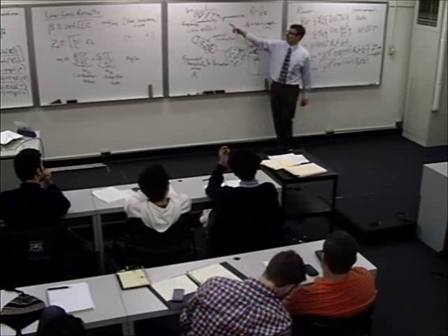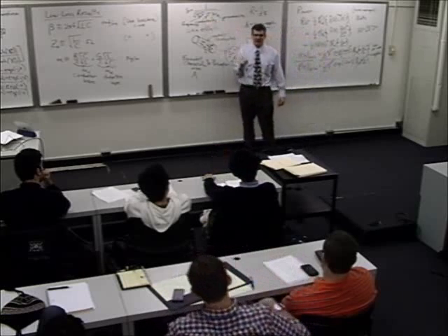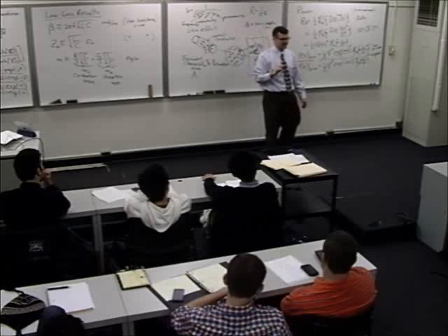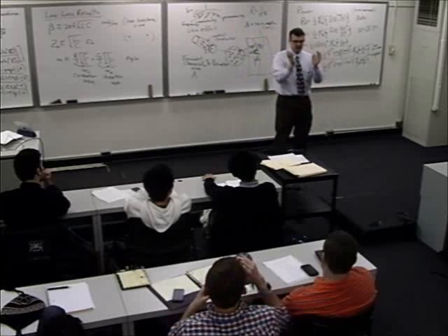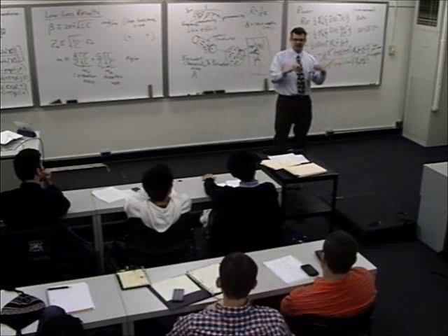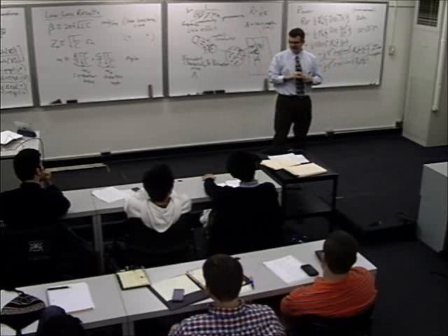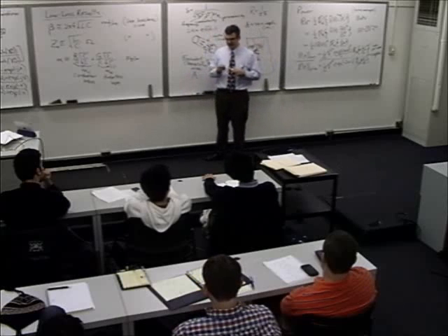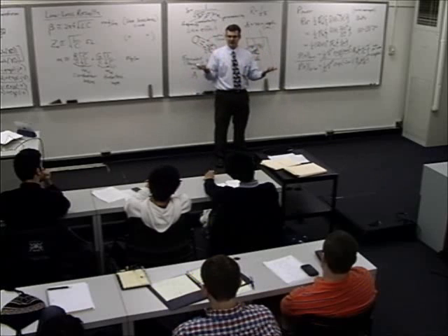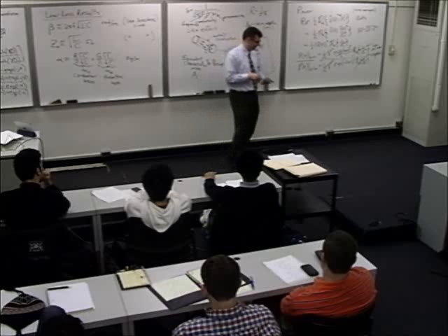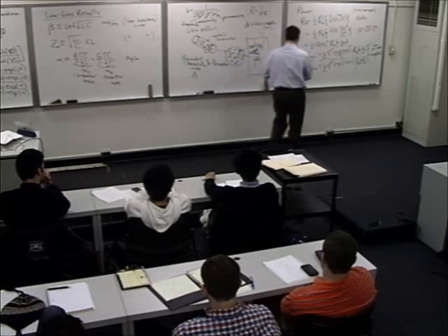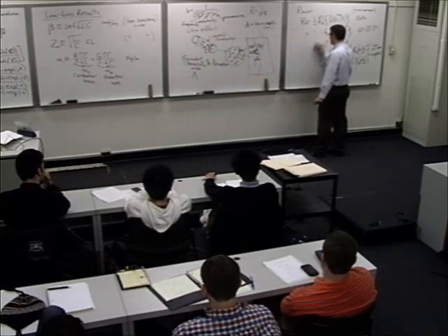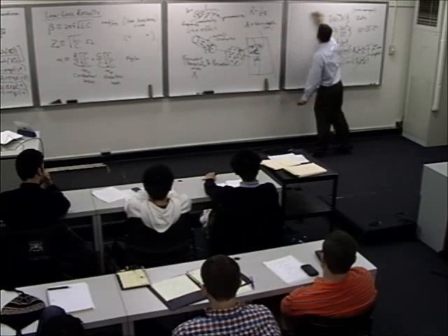The other thing to recognize is that there's a 1 over square root of F dependence in the skin depth. The higher the frequency, the closer things cling to the outside. We can see this in power engineering, this effect most readily if you just go outside and look at a high voltage line. And you'll see the different phases that they're carrying on the high voltage line, high tension wires.